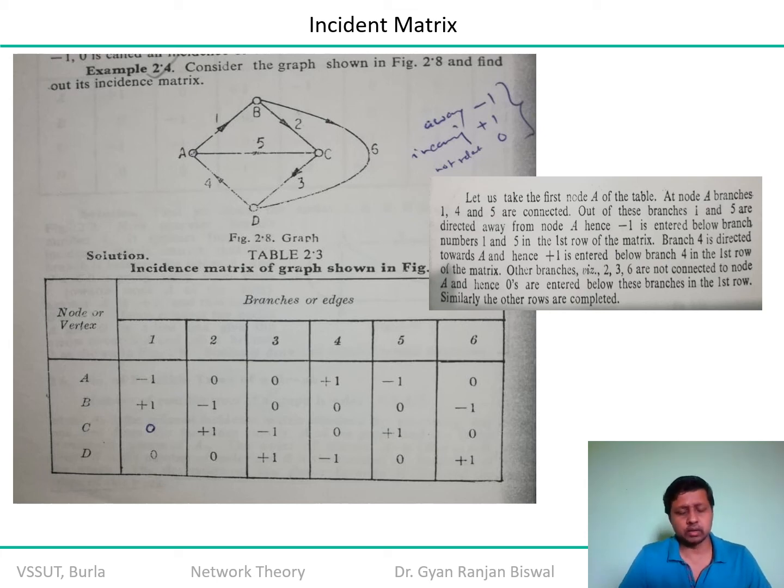At the end of the day, the common thing is that whether you consider the standard analogy or the assumed analogy, as some electrical or electronic science experts insist, either way works. If you establish the interrelation of this incidence matrix, how do you come to know that the solution you have found is correct or not? Here I will tell you how you can verify. There is a very simple approach. If you add the total numbers in any vertical section, which interconnects the participation of a particular branch with all possible nodes of that electrical network, that sum should always be zero.